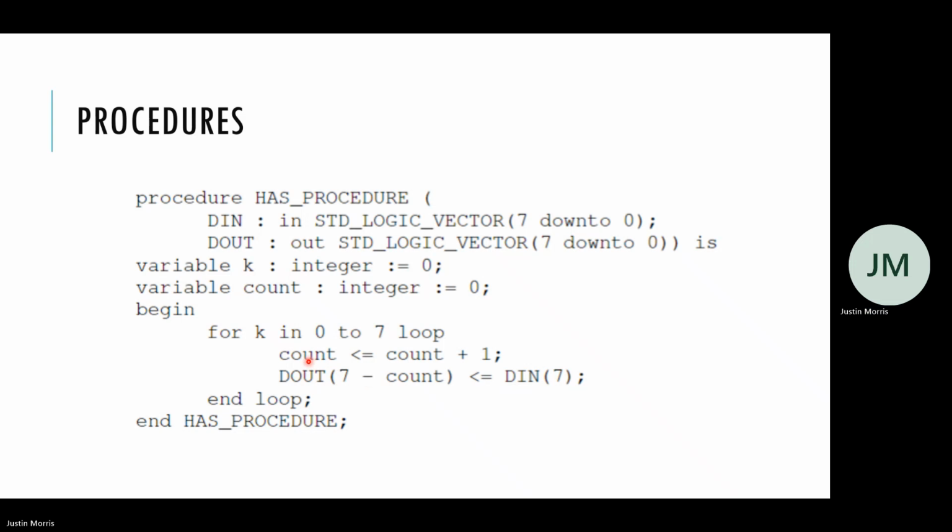So once we copy paste this for the 8 bits, our output is just 8 bits of the most significant bit from the input in this case, right? Because we're always din at 7. So all this procedure does is take the most significant bit of the input and copy and paste it to all of the bits of the outputs. Are we good with this procedure?